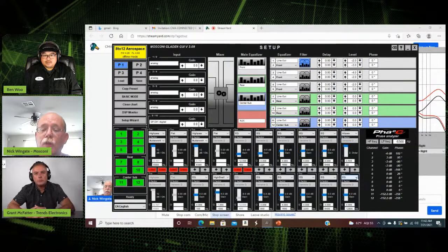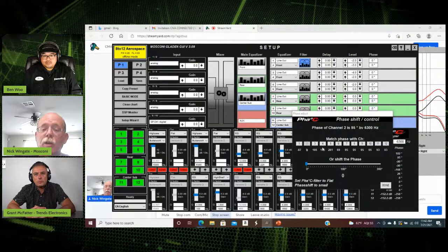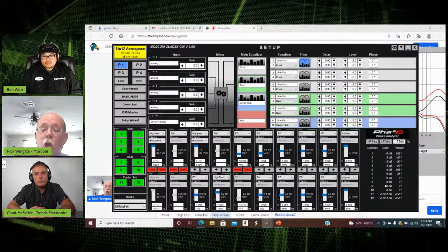Now all you've got to do is go correct the other side, channel 2 to channel 4, and you'll notice now it's not 355, it's 185 degrees. So it's a different second-order all-pass filter at 6,000 hertz. That's because of what took place right here. Oh, it's affected by the other.